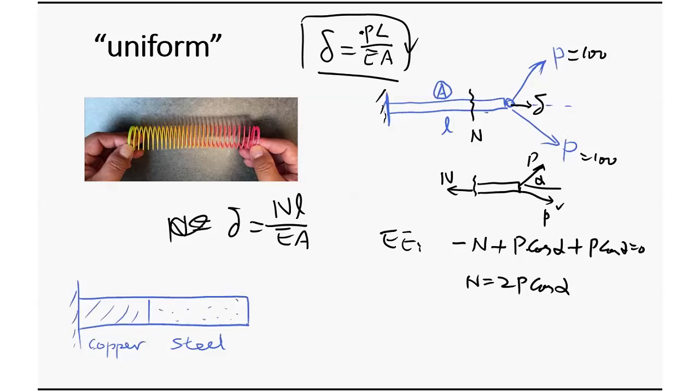So everything must be of the same bar. It's the force in the bar, length of the bar, material E of the bar, area of the bar. You cannot use somebody else's. It's your money, you use it. Your food, you eat it. So it must be everything from the same source. That's very important. Very obvious, but oftentimes we make a mistake. You will see later on. So I just want to emphasize that it's the local internal force. You have to use it that way. That's the first point I try to make.